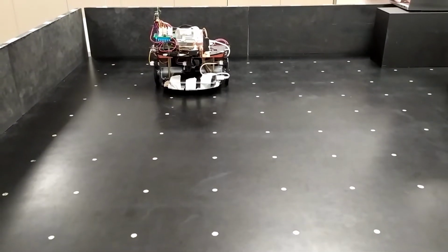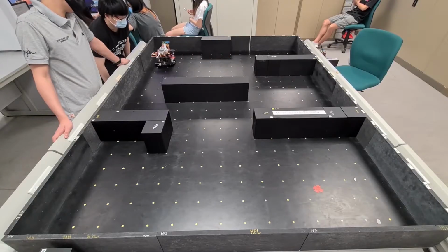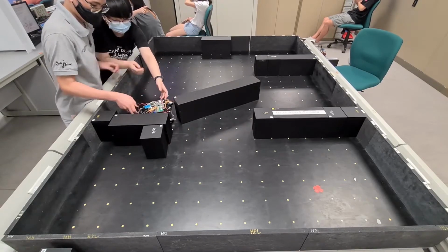Initially, the robot wasn't moving straight due to noise and variations in the environment, which results in uneven set speeds for both motors. This results in it deviating from the intended straight path and not being able to rotate left and right properly. The sensors were not giving us stable and precise readings as well.